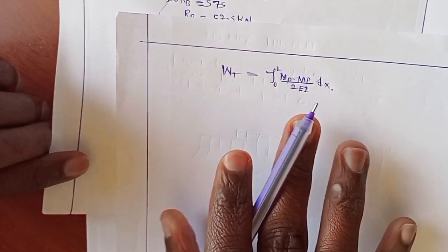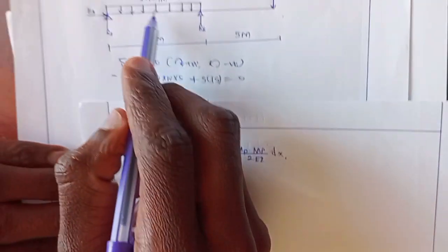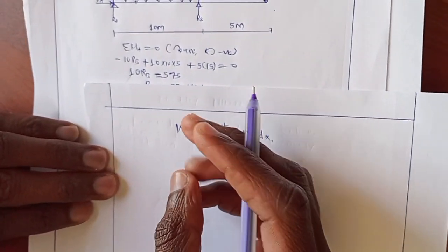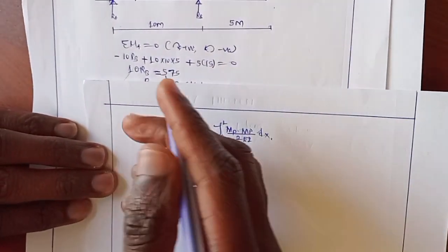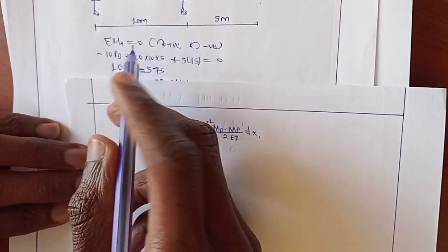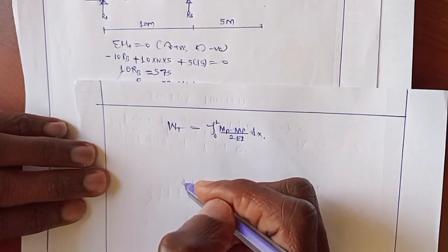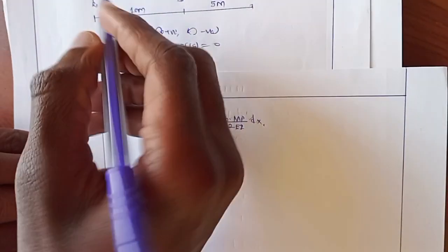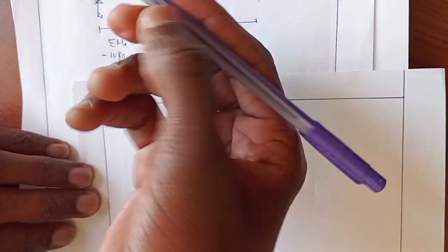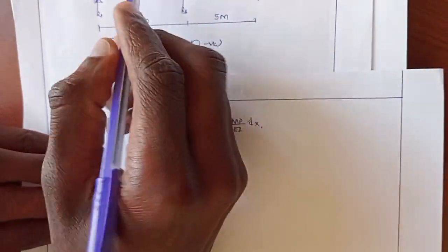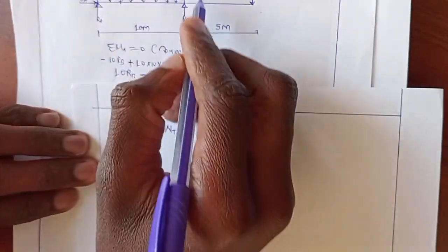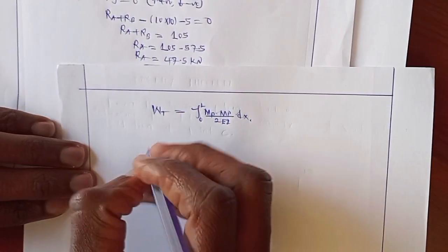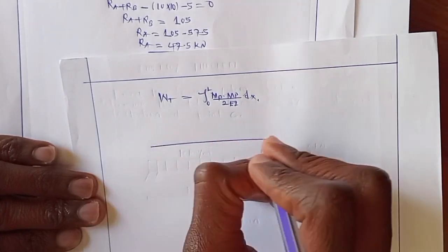we'll cut a section. We know when we cut any member at a certain point, internal forces are produced. Internal forces are the normal force, shear force, and the bending moment. So for this beam system, we'll cut sections at 2 points, at this region and at this region. So it will be in this way.